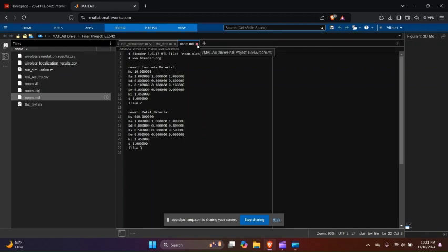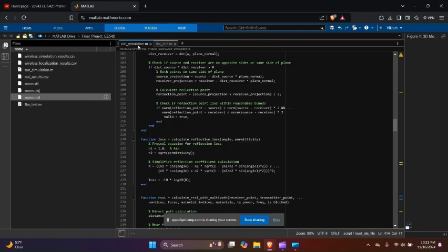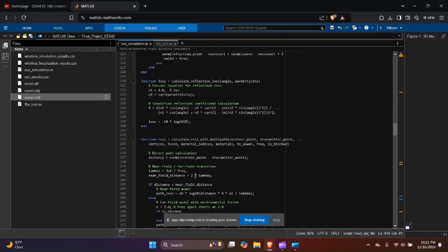So this is the next layer of sophistication we added to our model. This is definitely a much more advanced ray traced 3D model. For that, I now need to add some additional functionalities to the code, right? So not just a simple 30 dB loss if it is a reflected ray, but calculate the right RSSI for multipath signals.